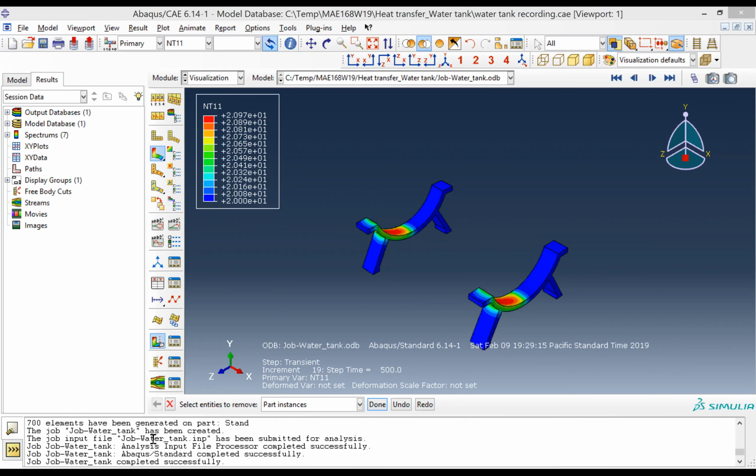I'm saying this because sometimes you can find some problem in the GUI that prevents you from completing the analysis. Sometimes there are some discrepancies in Abaqus between the input file and the GUI. What I mean by discrepancies is that the GUI makes some mistakes, and you can come here to the input file, follow the sequence, and detect errors, something that was omitted in the GUI. You can easily find here if there is any inconsistency. So it's like a double check that everything is right and looks as expected. All right.